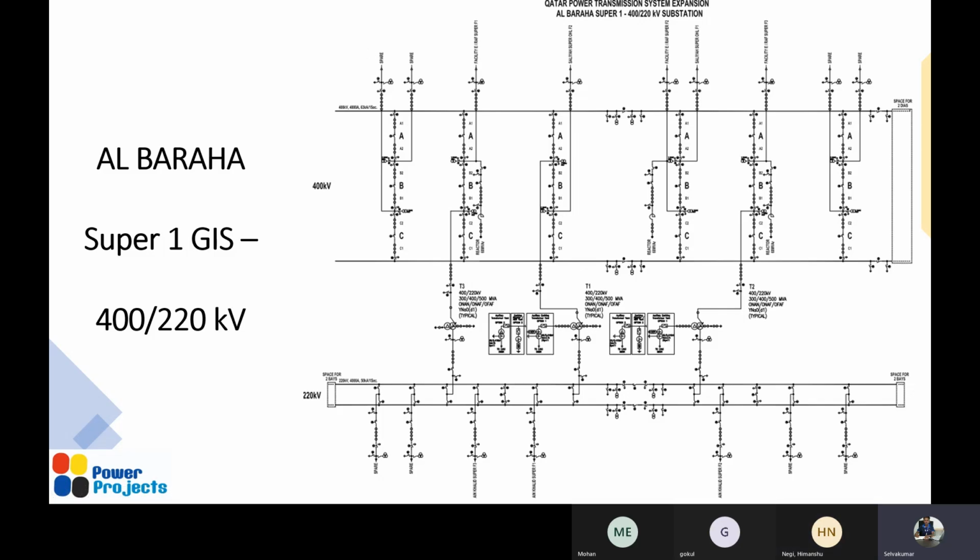So whether you are comparing with the T10 or T30 or T60, T100, that also will change. Okay, so this was the question, where I was saying that wherever you are using a breaker in operation, like transformer energizing or a reactor energizing, in every scenario you need to check the capability of this breaker.